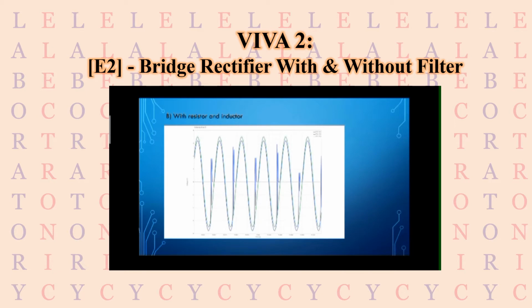For the half-wave rectifier with resistive load and inductor, the result is shown as below. The green line indicates the AC input voltage, while the blue line represents the DC output voltage with additional inductor. The gray line shows the waveform of a resistor at 50 ohm. In order to let the inductor work significantly, the frequency is changed from 50 Hz to 50 kHz throughout the whole experiment.